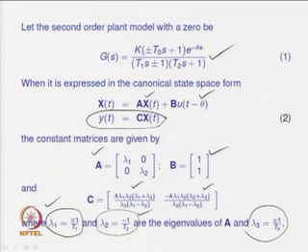So, for convenience we have chosen the 3 variables lambda 1, lambda 2 and lambda 3, such that the dynamics of the second order transfer function model is conveniently expressed in state space form, where A is equal to [lambda 1, 0; 0, lambda 2]. Let me repeat, why I am repeating this again and again: the form of A is such that it is possible to take the matrix exponentiation very conveniently, and that is not the case when A is not available in diagonal form.